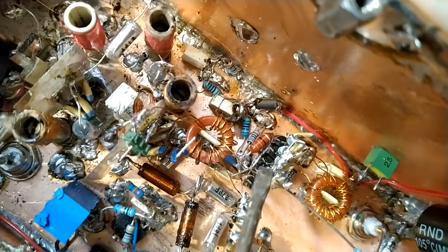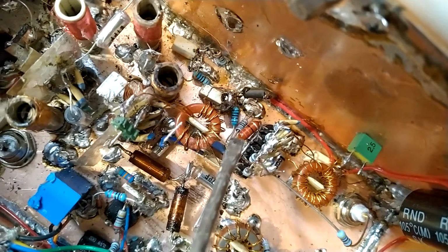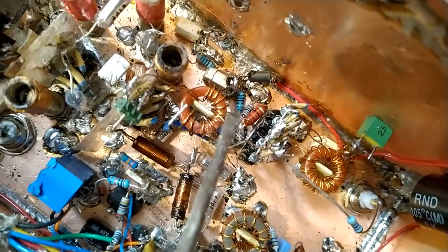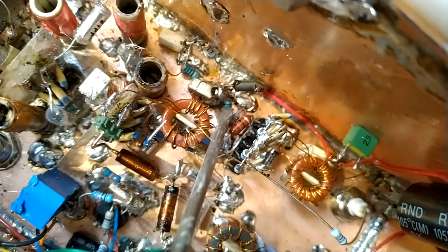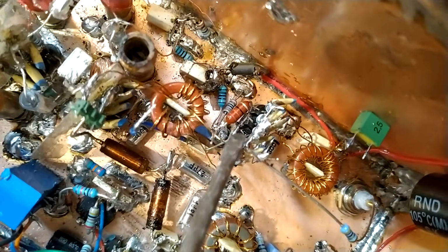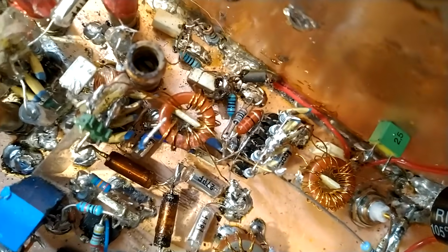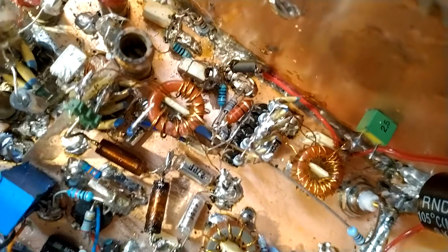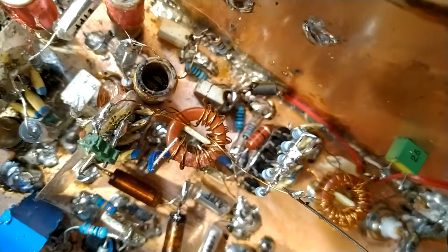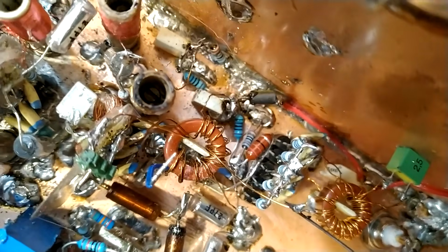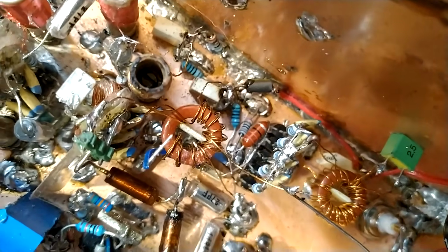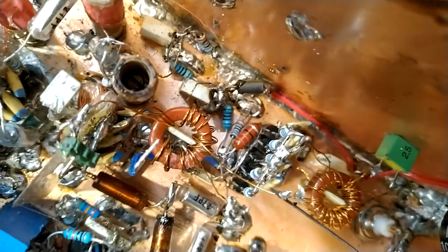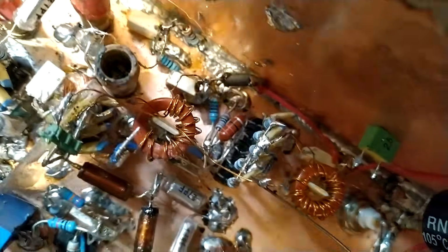I have moved the 4 560 ohm resistors in the bias voltage for each amplifier stage to place them very close to the laminate, and then a small quantity of epoxy to make them in good thermal contact. They develop about 300 milliwatts each, so they may cause some circulation of air around them. But now they will heat the box walls that will spread the thermal energy around better, I think.